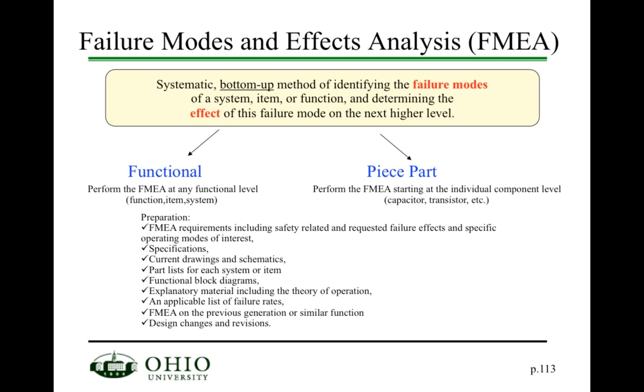Now, the failure modes and effects analysis is so late in the life cycle model that at that time we know what the design looks like. So we have all the detailed information regarding very low level design, regarding failure rates of components, etc. So in the failure modes and effects analysis, we take a bottom-up approach to identifying the failure modes, and we check what kind of effect this failure mode has on the next higher level.